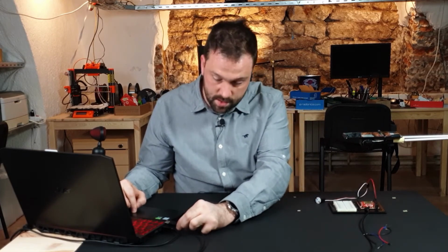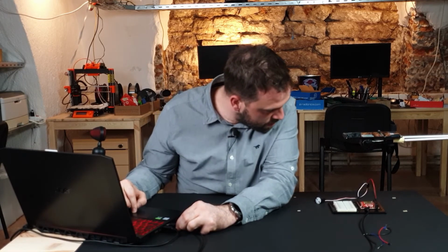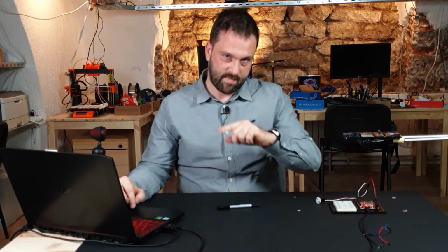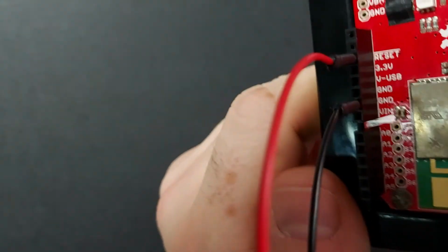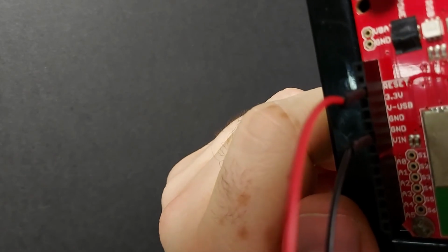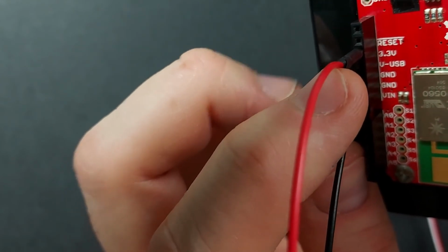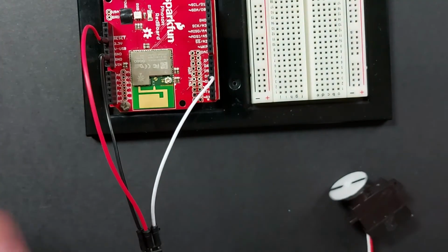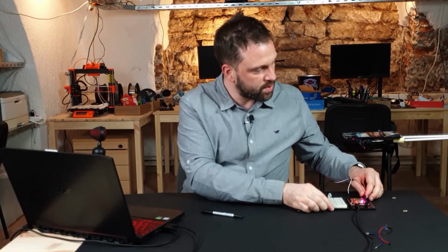Interesting. Just a second. Okay, I made a mistake. See, it's the same thing that I warned you not to do. I put my pin wrong, so I connected basically ground and reset. It means that the board is always resetting. I missed the hole, it should be 3.3. Now I can start the board. Yeah, it's okay, and I can initiate flash. Don't do that, okay? I do these things so you don't have to. Now you know what happens when you connect reset.